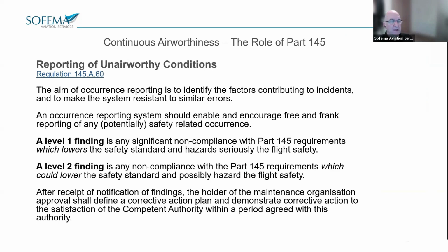Reporting of unairworthy conditions. Now, this is about occurrence reporting. So the aim of occurrence reporting is to identify the factors. So it's for our future use, really, in making the organisation safer, such that we don't repeat errors. A certificate of release to service under maintenance is a verification and statement there are no known non-compliances which would endanger flight safety at the point of releasing the aircraft maintenance.